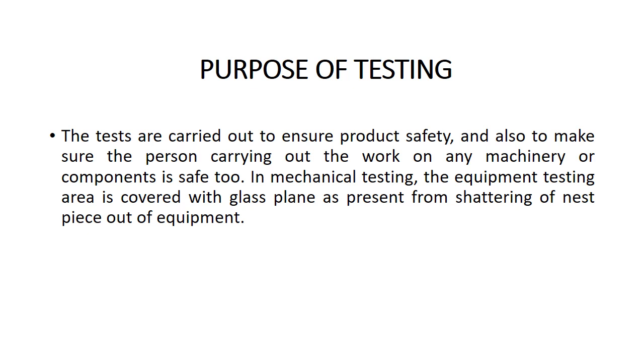What is destructive testing? Destructive testing is a form of object analysis that involves applying a test to break down the particular material to determine the physical properties, such as mechanical properties of strength, toughness, flexibility, and hardness. It is undertaken in order to understand the specimen performance or material behavior. The procedure is carried out on the test specimen up to the failure.